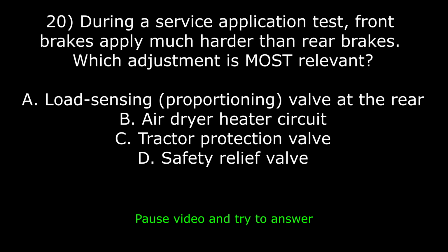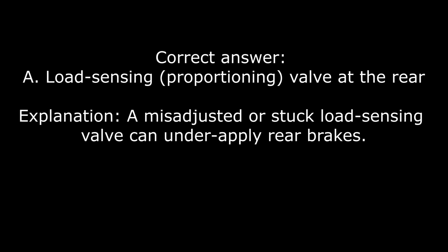Question 20. During a service application test, front brakes apply much harder than rear brakes. Which adjustment is most relevant? A. Load sensing or proportioning valve at the rear. B. Air dryer heater circuit. C. Tractor protection valve. D. Safety relief valve. The correct answer is A. Load sensing or proportioning valve at the rear. Explanation: a misadjusted or stuck load sensing valve can under-apply rear brakes.